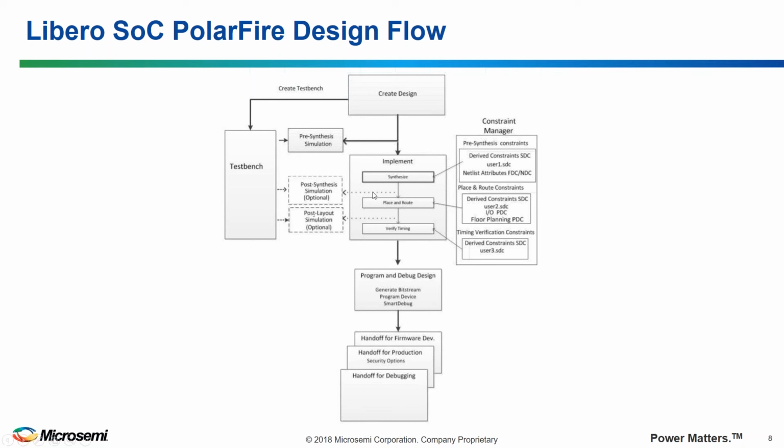So in Libero SoC PolarFire, we have a constraint manager that allows you to create and manage all of your constraints for all of the design implementation steps. And as you go through some of the implementation steps, like synthesis, for example, you can actually run a post-synthesis simulation. Same thing after layout, you can export your delay information in an SDF timing format file, and you could run a post-layout simulation in addition to running the static timing analysis tools.